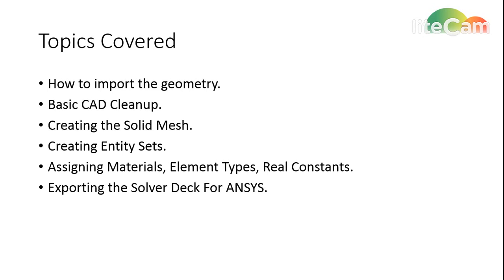Ansys APDL, we have to do some more steps, and that will be creating the entity sets, creating the materials, assigning those materials, element types, and the real constants. And then we'll export the solver deck for Ansys Mechanical APDL utility. So there will be a series of tutorials wherein I will show how to create a solid mesh in Hypermesh and then solve the same model in Ansys Mechanical for various cases.